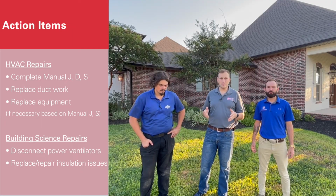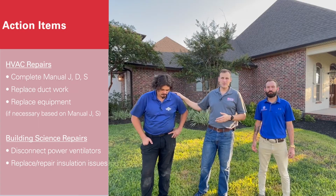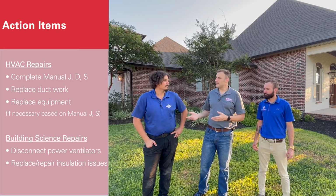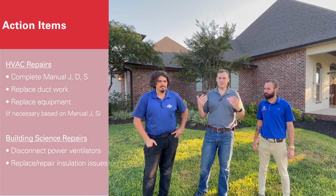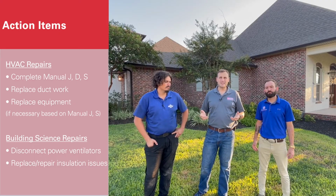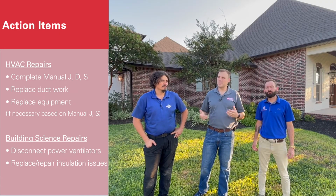Now, during the walkthrough, we identified that we had power ventilators, which we would probably wrap up under the building science side of things. That's probably definitely an issue, right? We're probably pulling the house into a negative. We would have loved to have done that with a dominant duct leakage test, but we had a little bit of wind today, so it wasn't the proper day to do it.